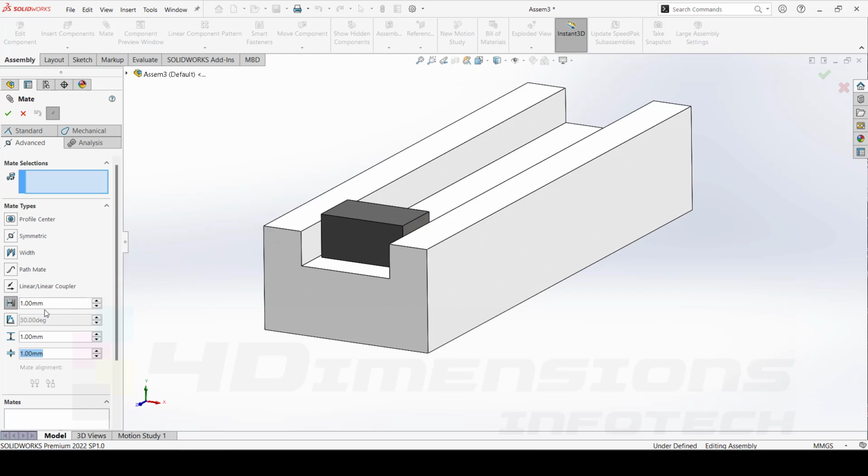So in advanced mates, for distance mate, we have to apply two distances, maximum and minimum. The initial distance is given beside the symbol of distance mate. So I'll take the initial distance as 0. The values that matter here are the maximum and minimum value. The maximum value I'm going to take here is 110 mm and the minimum value is 0 mm.